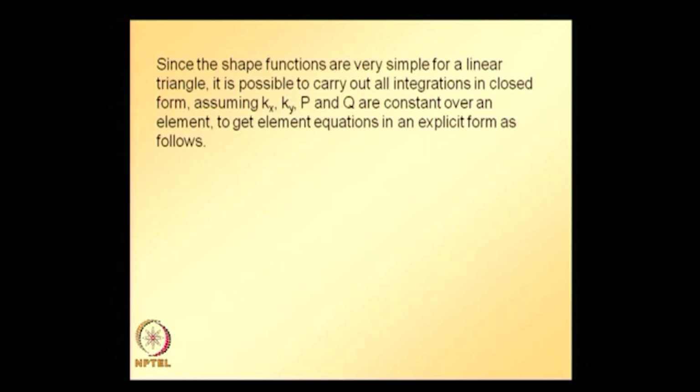Since the shape functions for a 3 node triangular element are very simple, since it is a linear element or linear triangle, it is possible to carry out all the integrations in a closed form, assuming kx, ky, p, q are constant over the element, to get element equations in an explicit form.